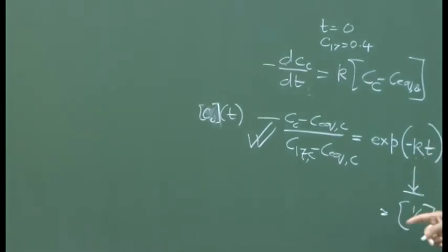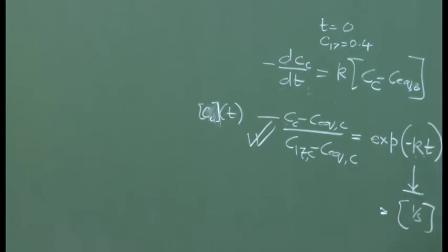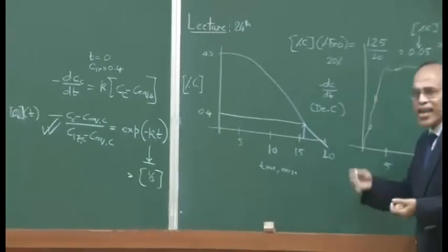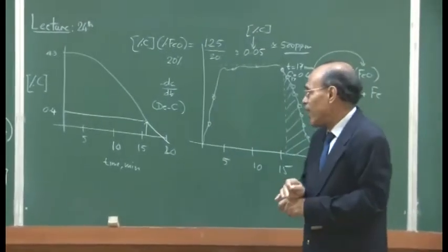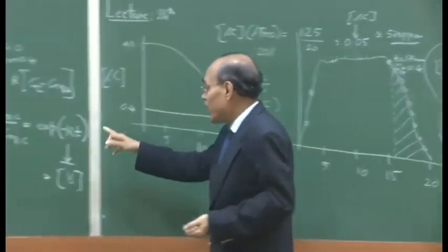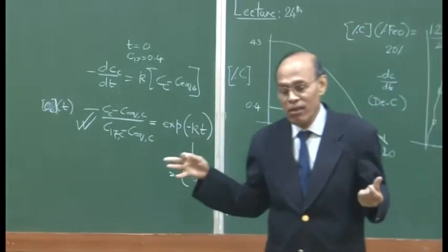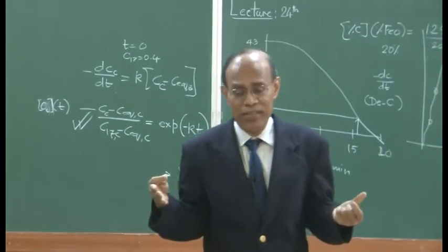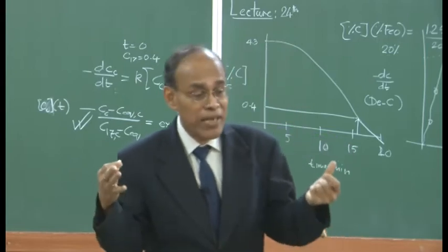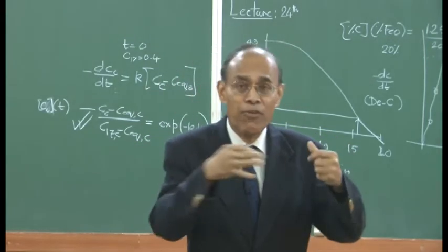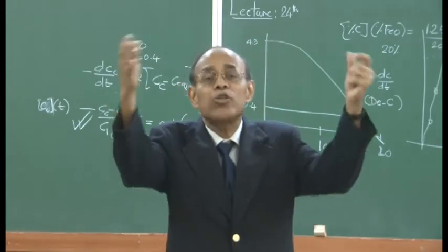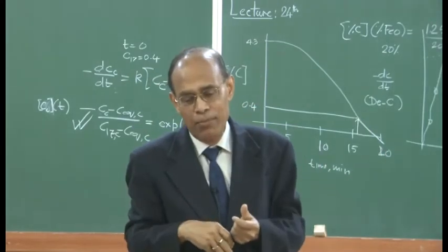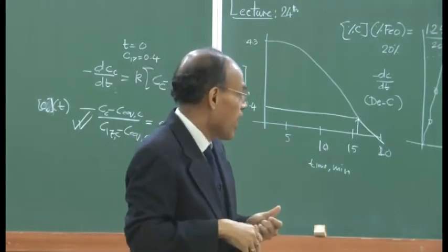And as such you will see, because the high temperature measurements are concerned, the certainty with which K can be determined will vary from plant to plant. So, innumerable experiments, trials and adaptations need to be done, and these rate constants are going to be in a mass transfer control process. For example, you will measure during the first set of heats and the last set of heats, because the refractory design etc. because of erosion and corrosion have changed.